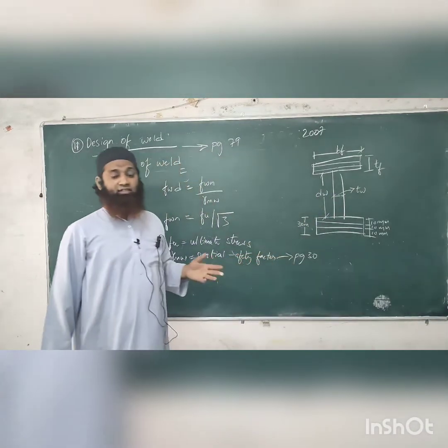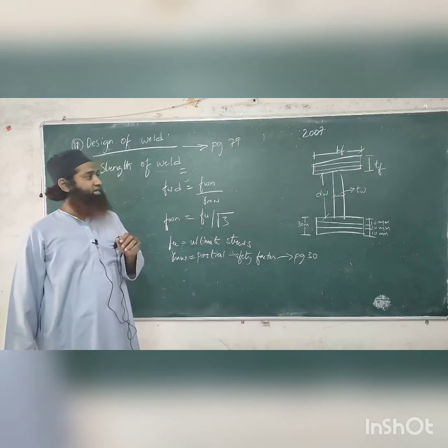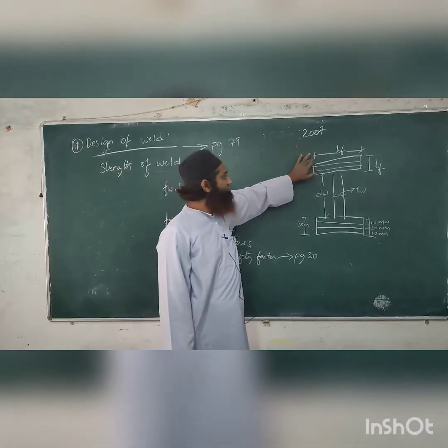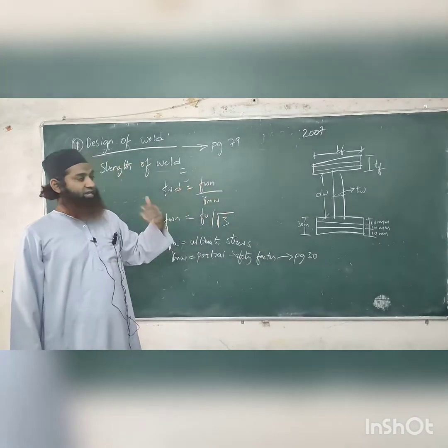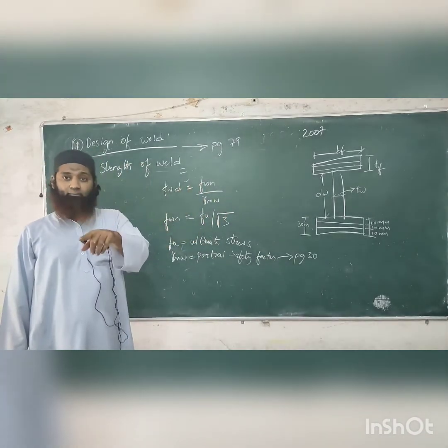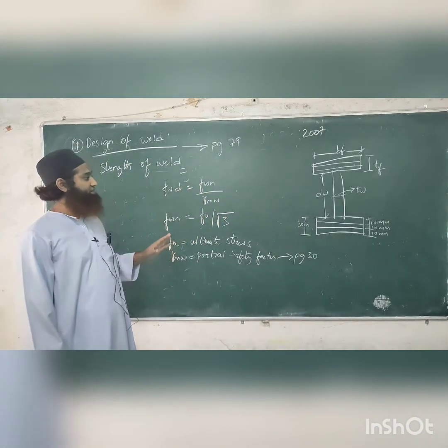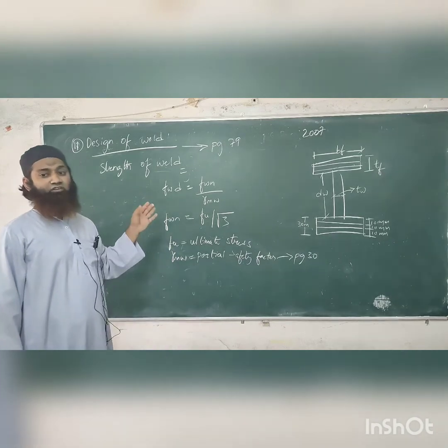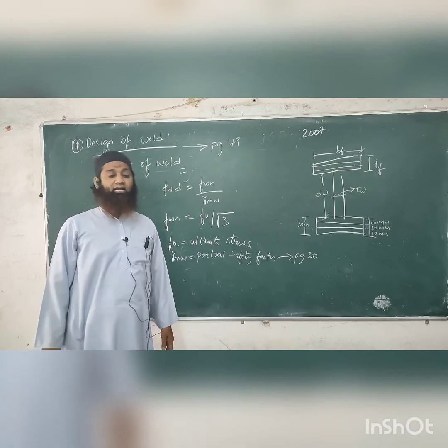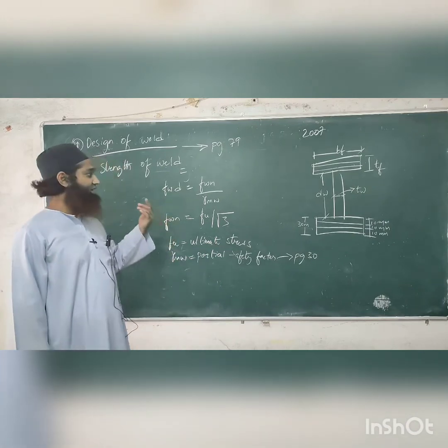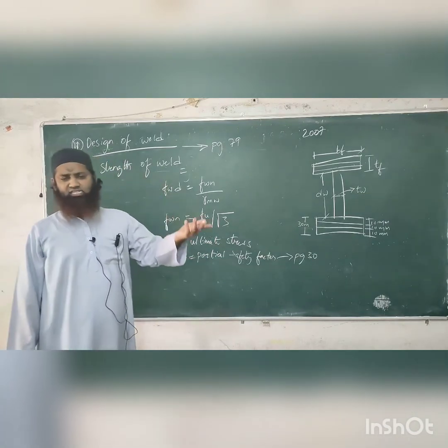Next we went for the design of the flange. We had seen the breadth of the flange and thickness of the flange. So till here we had designed the web and the flange. Next we checked the moment capacity. MD we had checked, given by the equation, and the design moment should be greater than the maximum bending moment, as I had told you. That was step 6 most probably.